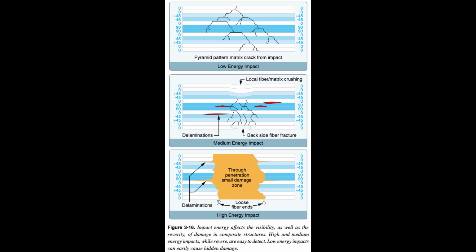Also, chemical paint strippers are very harmful to composites and must not be used on them. If paint needs to be removed from composites, only mechanical methods are allowed, such as gentle grit blasting or sanding. Many expensive composite parts have been ruined by the use of paint stripper, and such damage is generally not reparable.